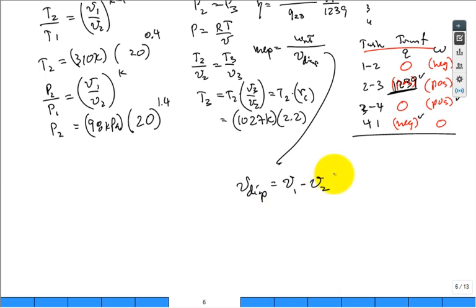Is the ideal gas equation always valid? Sure. So I can replace V1, or how do I calculate V1? It would be RT1 divided by P1. Likewise, RT2 divided by P2. Is that one way to calculate the displacement volume? Remember, PV is equal to RT.